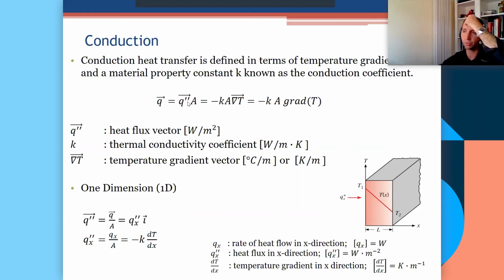So let's talk a little bit about that. A different notation for the rate of heat transfer. So Fourier's law of conductive heat transfer is what we have right here. Q, rate of heat transfer, is proportional to this quantity, which is the exact same as this. That is, this is the gradient of temperature. It's a vector. We've just discussed that. But it's also proportional to the area.